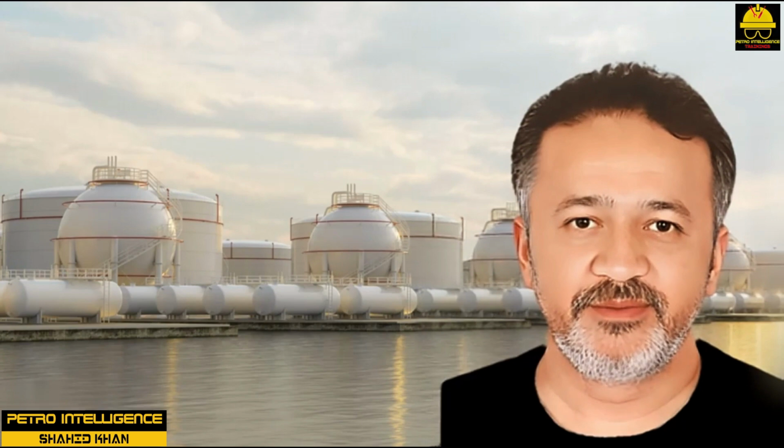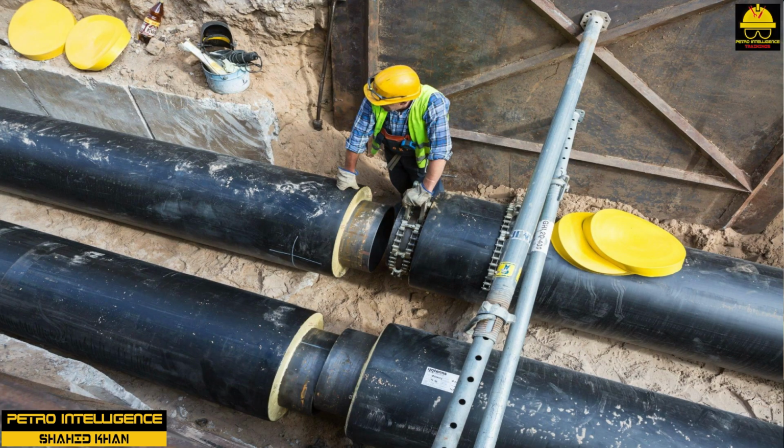Joining pipes. Almost all piping in critical services is joined together by welded joints, which provide much more strength and less chance for leaks than do threaded joints. For piping that is not critical, as far as pressure or contents is concerned, piping with threaded joints is generally much cheaper and easier to install than is piping with welded joints.